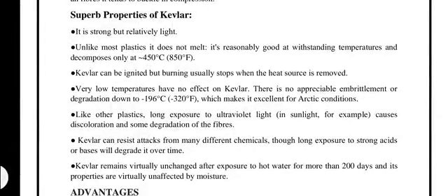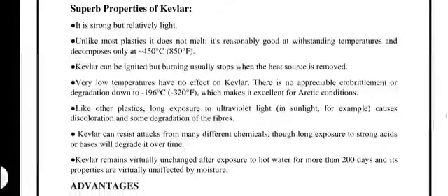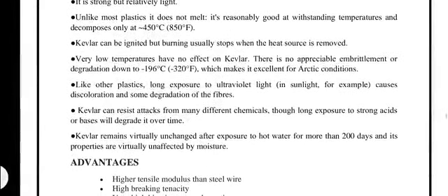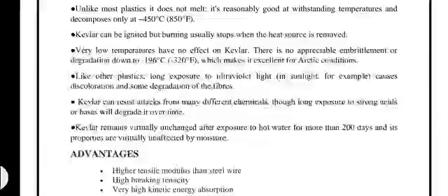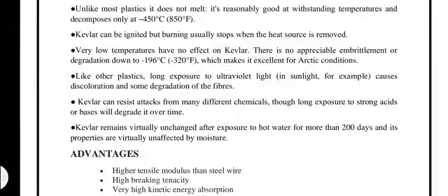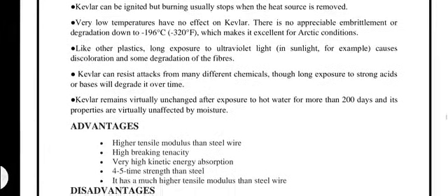Next are the super properties of Kevlar. The first property is that it is strong but relatively light. The second one is that, unlike most plastics, it does not melt. It's reasonably good at withstanding temperature and decomposes only at around 450 degrees Celsius. Kevlar can be ignited, but burning usually stops when the heat source is removed.